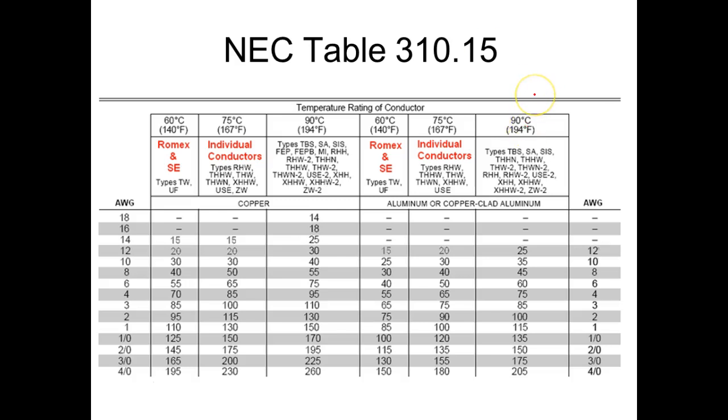Most of the cable I ever bought was Romex. 14-2 or 12-3. Or 14-3, or 14-2 with a ground. Yeah, that's right. So 12 gauge is rated at 20 amps and 14 gauge is rated at 15. And as long as you maintain that. So this is like an average would be for the United States? No, National Electrical Code, it's our code, it's for the United States. So Europe and all of them have their own electrical codes. You were talking about the equator. Well, I was wrong with it. Anywhere in the United States, this should do it.